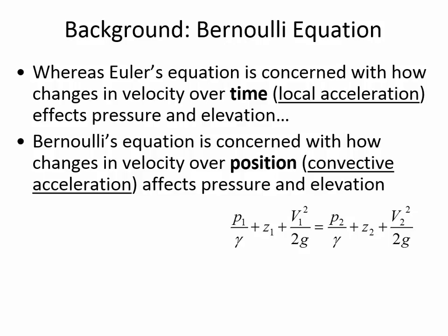That's true. Yeah, the influence of friction is less at the center line, but remember, when we usually apply Bernoulli's equation, the most common thing is to use the average velocity rather than a measured velocity. And so if you're using the average velocity, it takes into effect the entire cross section, the top, the bottom, in the middle.